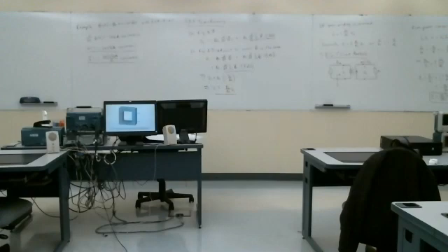So with assumed positive at the dot for both voltages, then V1 over N1 is equal to plus V2 over N2, or V2 over V1 is plus N2 over N1. The dot convention just helps you determine whether you have this plus relationship or this minus relationship.